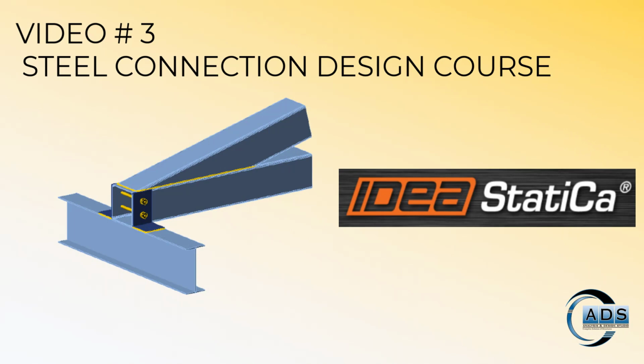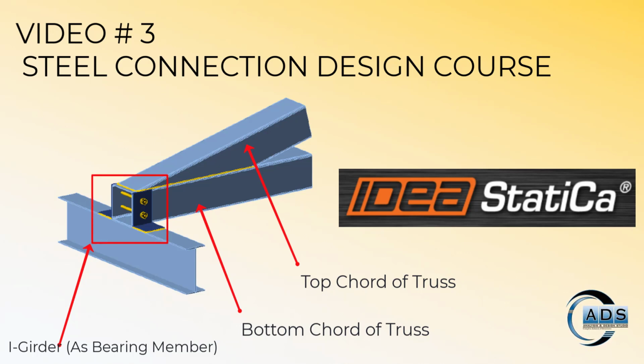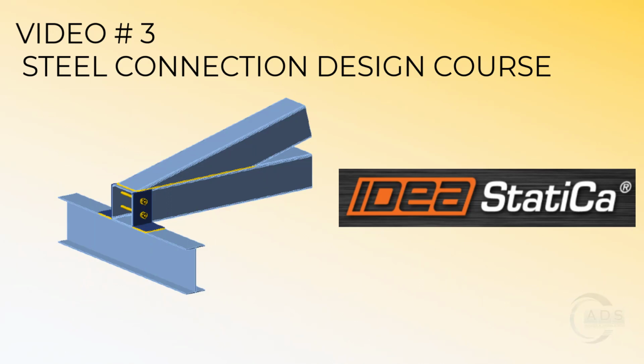In this connection, this is the I girder, and this one is the bottom chord of the truss, and this one is the top chord of the truss. These two chords are seated on this I girder with the help of a cleat angle. This cleat angle is welded over the top flange of this I girder and bolted into the bottom chord of the truss. So let's move on to the software screen.